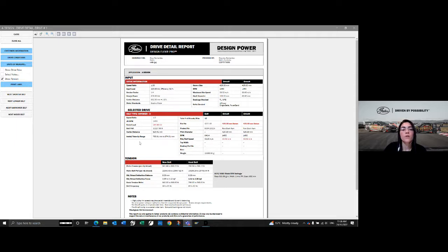We have a problem. So let's say I want to use one more belt and see if it's working. In that case, you have options to put a shorter belt, longer belt, narrow belt, or wider belt. Shorter and longer belt will obviously change your center distance. Narrow belt, you use fewer belts, or wider belt, you use more belts.